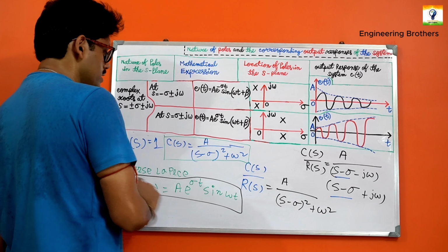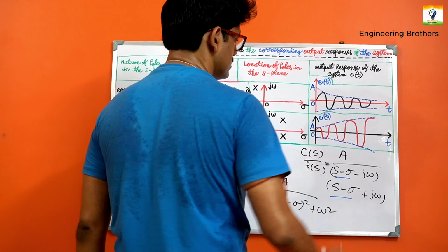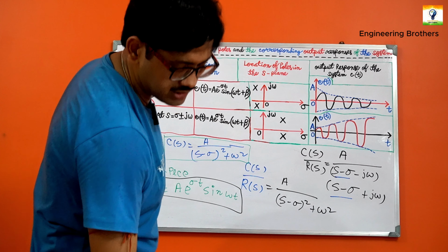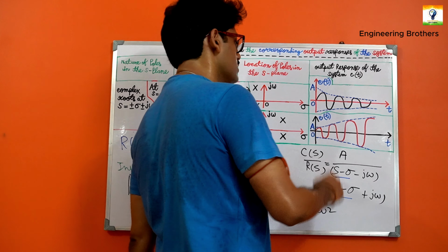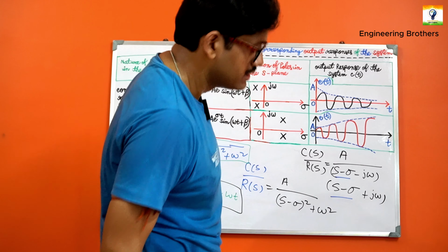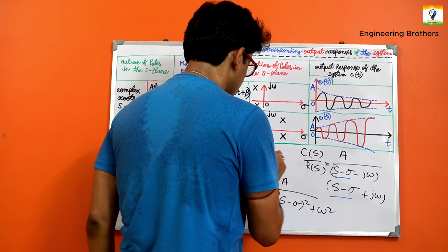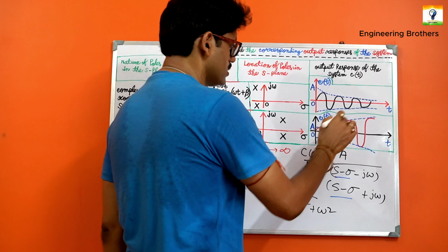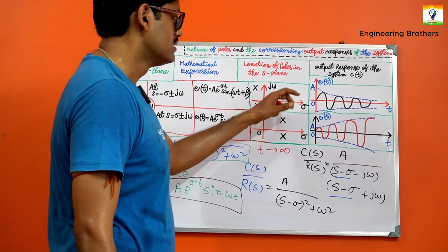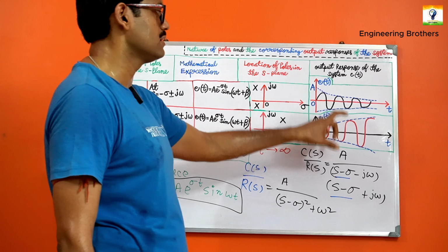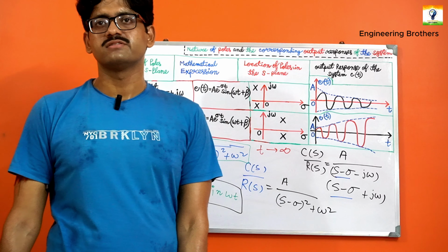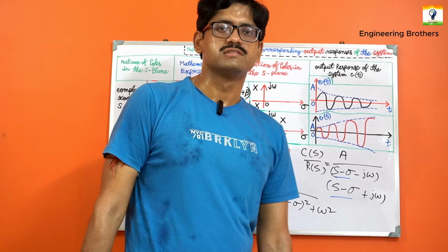And if we plot that in our c(t) versus time curve over here, we have realized that the waveform has started from 0, and if you increase the time, which is the time t tends to infinity, for that one the oscillation is increasing. You can see that the oscillation is increasing with respect to time over there, and that gives us the characteristic of our unstable system over there.